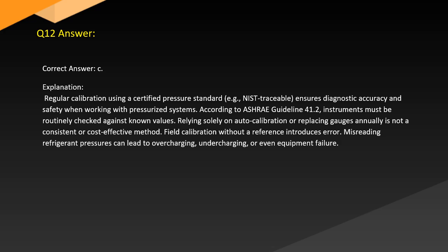Relying solely on auto-calibration or replacing gauges annually is not a consistent or cost-effective method. Field calibration without a standard introduces error. Misreading refrigerant pressures can lead to overcharging, undercharging, or even equipment failure.